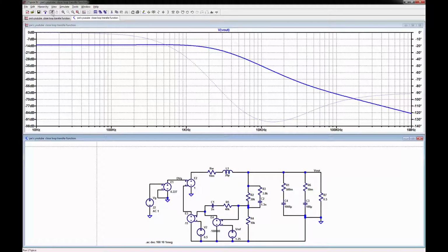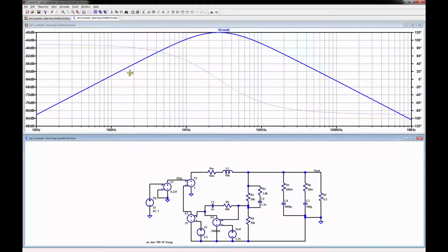And we run it again. And there it is. It comes up and it comes down. Because remember, the LC filter started coming down here at a -2 slope. This is a +1. This was a -2, so you get a -1. You get a +1 and a -1.